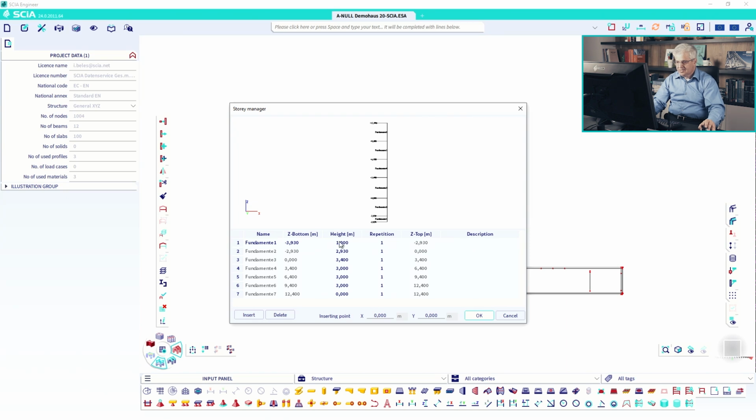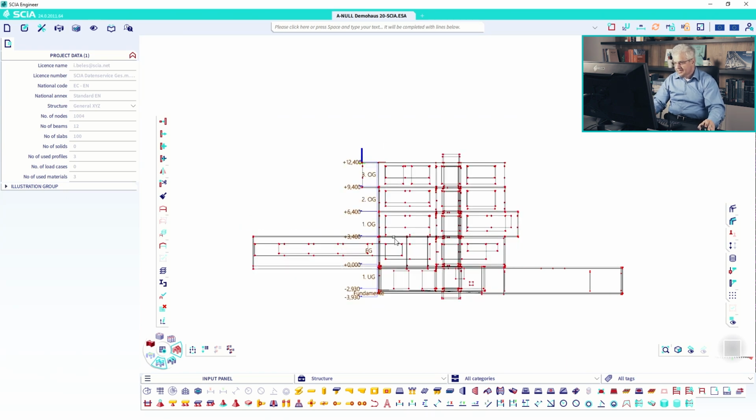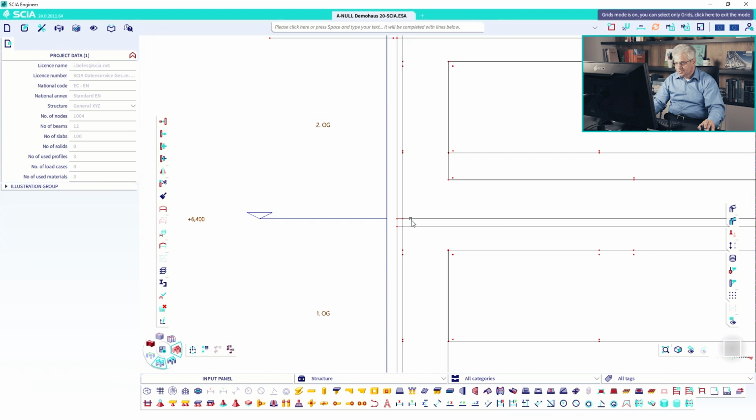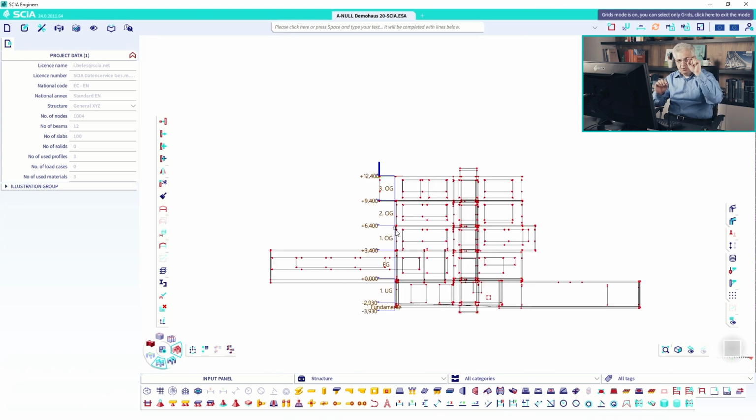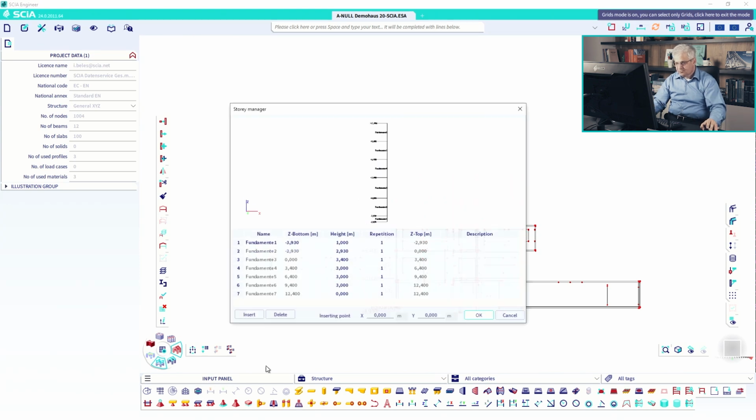use stories. So we need the correct heights. Usually the height is not on the plate, but on the top of the plate. So you need the stories at the center of our plates. So we have to go to the stories and write the correct value. I have calculated it before. Minus 0.01 is on the bottom. Then we have 0.58, 2.93, that was okay. Then we have 3.775. Then we have 3 meters 3 times, and then on the top 0.7 times 2.5.